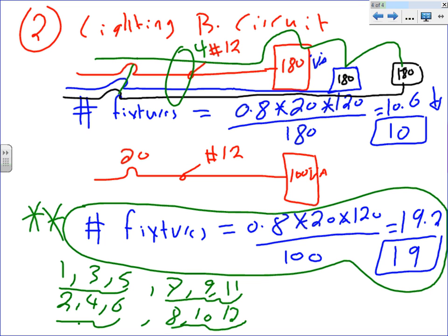You don't ever go 1, 2, 3, 4, 5, 6, 7, 8, because that will get you. Physically, mechanically, guys, you're going to end up with circuit 1 here and circuit 3, 2, all the way down in another room. You could put them on the same neutral, but it will be a waste of money. You already moved to a different room, and you'd have to drag your neutral all the way to a different room. So, any questions, guys, about lighting and receptacle circuiting? That's exactly what chapter 4 Spencer was talking about.